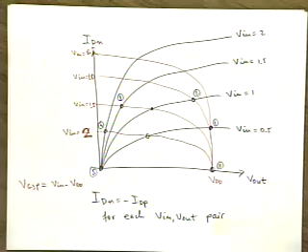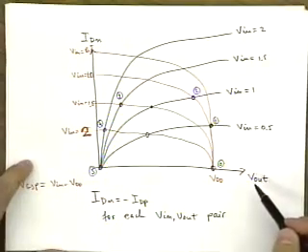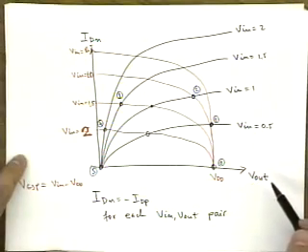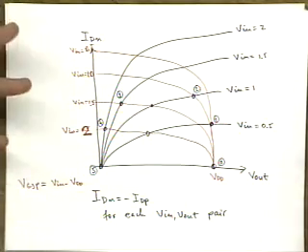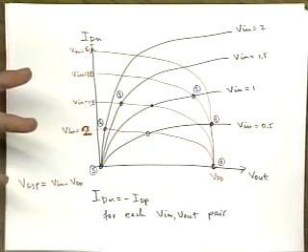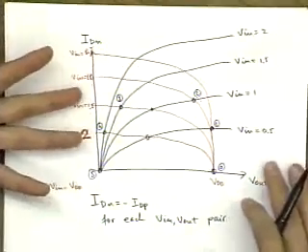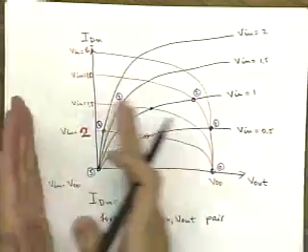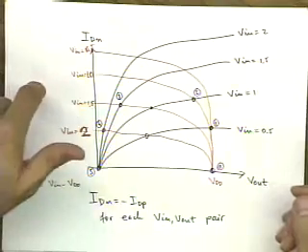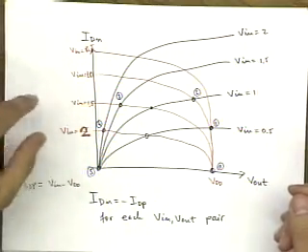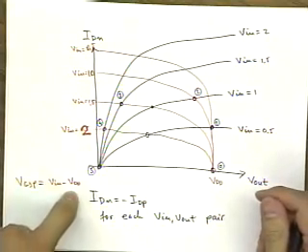Okay, let me then highlight important points here. So step number 1, you have this ID versus V out family of curves for NMOS. Then you have to transfer PMOS load lines into the coordinate system of this NMOS device. So you have to do 3 things. You have to flip over the sign for the PMOS current, then you have to shift it over for the VDS over here, and then you have to flip the labeling on VGS, because you have this relationship that V in is equal to VGSP plus VDD. Okay.